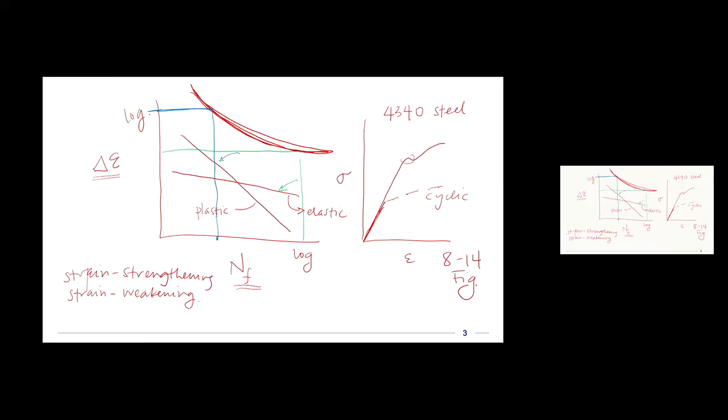So we really are just saying that the strain amplitude is the sum of an elastic strain amplitude and a plastic strain amplitude. On a log-log plot, each of those would be represented by a decreasing power law type function, each one a coefficient times the number of cycles to a minus power. That would give us these decreasing lines here that would sum to a curved line there. So that's the concept that was presented in the last lecture.